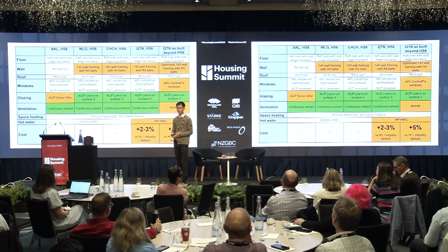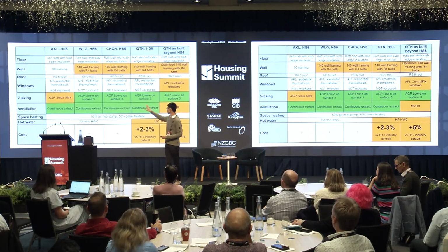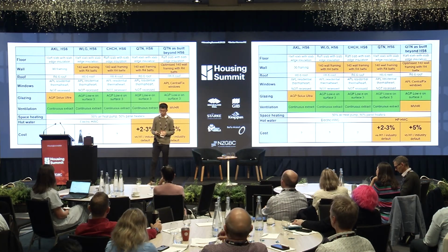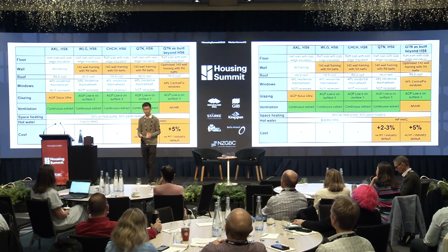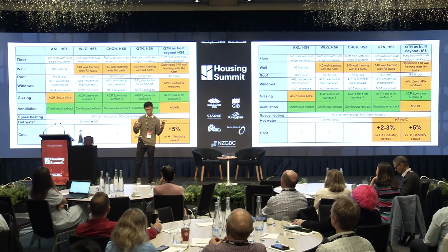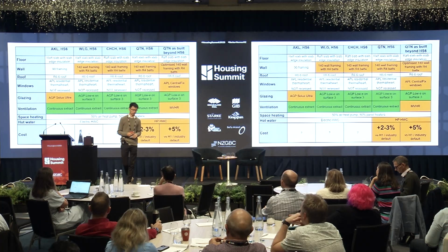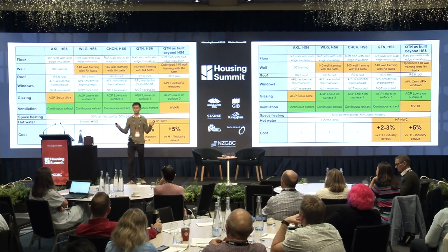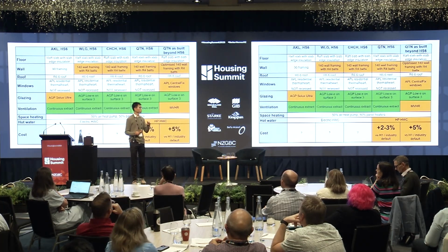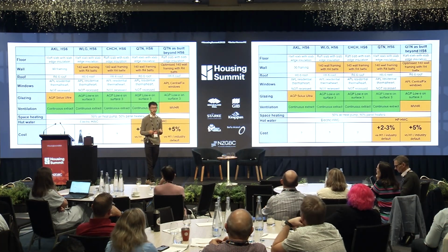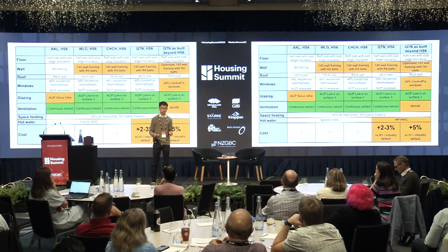If we copy and paste the exact house to Christchurch and Wellington, the thermal envelope itself is pretty much the same, but we don't need a hot water heat pump anymore. In Auckland, we don't need 140 framing. However, with the hotter climate, unless we resize the window, which is probably a good thing, it might trigger the use of a more expensive low-E glazing. So I do hope this gives you an overview of the requirement for both specification and the relative cost uplift you might expect when doing a Homestar project under the current version.